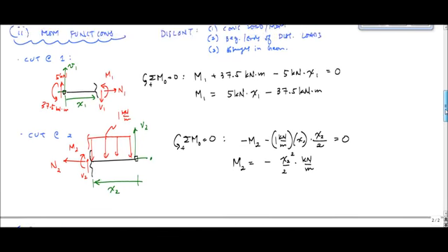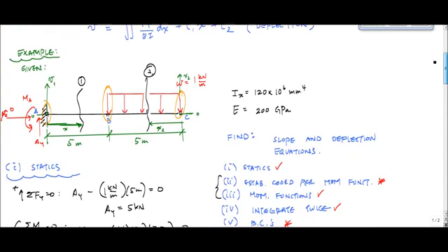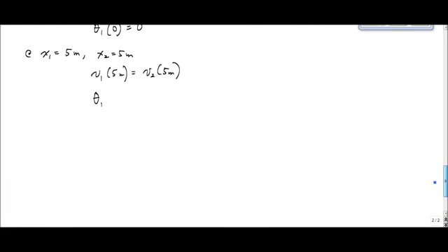Okay, now check this out. This is where everyone gets messed up. Here is that the slope theta 1, right here, if I could visualize my deflected shape, here's what my deflected shape looks like. I know this drawing is getting really sloppy, but let me draw it down here. Here's my cantilever, like this. Here's my fixed support right here. And here is some distributed load going across like that. And my deflected shape is going to have 0 slope and 0 deflection here, and then it just curves down like this. I've totally exaggerated it, but this is what it looks like.